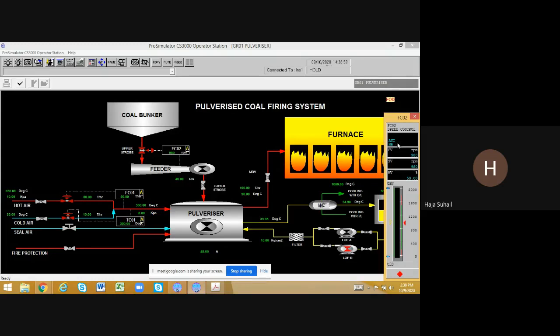We can change them by selecting the AUT. The AUT is here. This is the actual description of the automatic controller, so it is in the auto mode. When I click that, you can see a pop-up with three icons. The first one with the hand symbol is the manual mode, the cycle one is the auto mode selection, and the third one is the cascade mode selection.